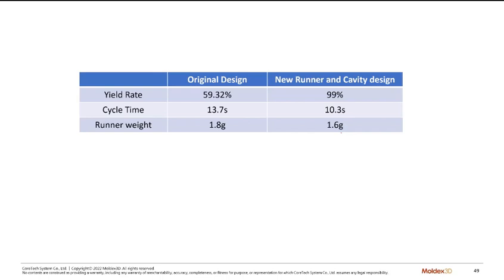And by fixing the weld line issues, they change the thickness near the pin, because in the original design the thickness is too small. It's less than 0.1 millimeters, and the material will have a very low melt front temperature when the weld line happens. Once they remove the thin features, you have a better weld line quality. It mixes at a higher temperature, so the quality is better. Then they heal the crack issues.